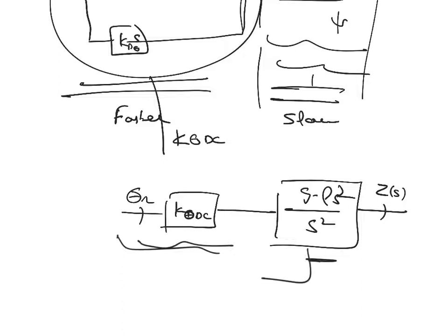And you will see also an example in UAV. For example, when the UAV has to change its heading, it rolls first. When it rolls, its heading changes. So what do you think must be faster? This roll should be faster, or this heading change should be faster? The roll, right? It rolls kind of immediately. But say you have to change 10 degrees of heading, it might take 2 or 3 seconds to change the heading. But roll changes immediately. So that's our design, that we are choosing that separation between these two loops.